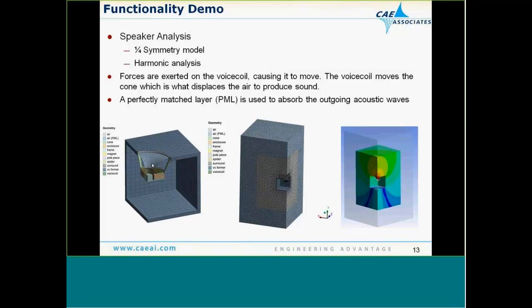And the idea here is to look at the pressure, the acoustic pressure, and the sound pressure levels in the air at different locations. So this is a quarter symmetry model. All right, so we're just modeling 1/4 of the speaker and the speaker cabinet with all of its internals, and then 1/4 of the air surrounding that. And we'll do a harmonic analysis.